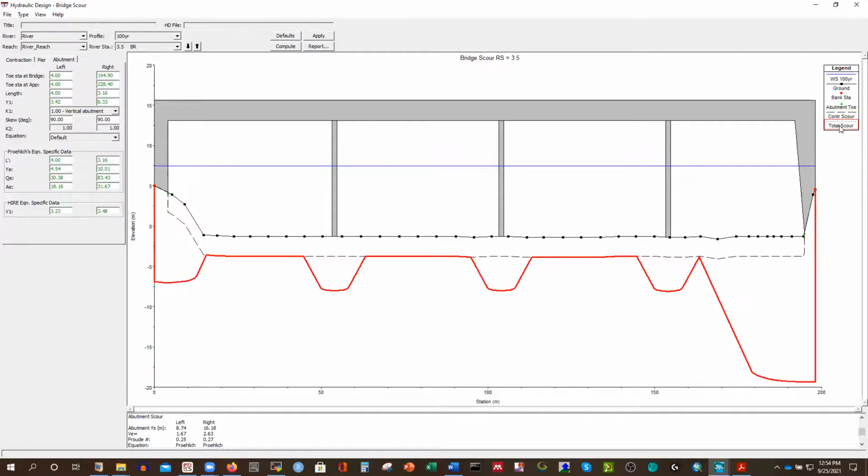And then total scour, can you see that? That is what we need, total scour. So this abutment on the left side, we have less, what is the value? We don't know the exact value, we'll see that from the report. It is even like 6, 7, 8, and there on the right side, you have like minus 20. Can you imagine? So you have to treat that.